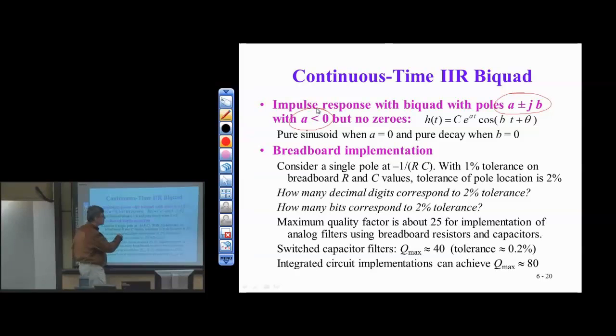If you do the inverse Laplace transform, you get a very familiar decaying sinusoid from all those differential equations you've solved in the past for the linear constant coefficient case. Very familiar. So this is the impulse response of such a biquad, again, providing the initial conditions are 0.